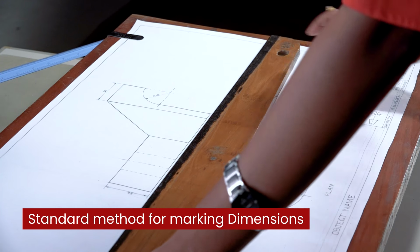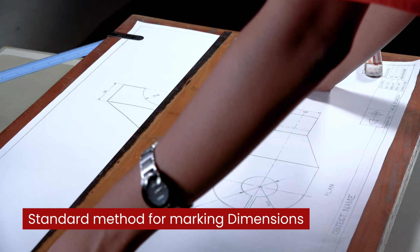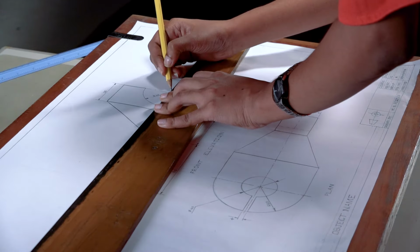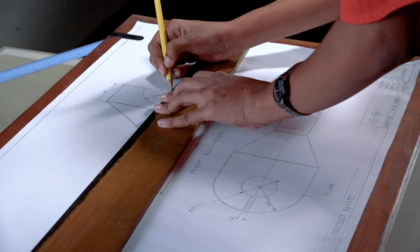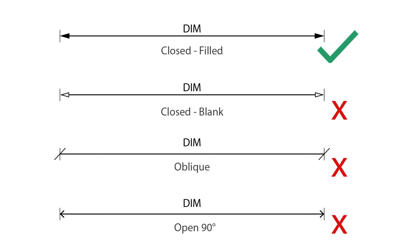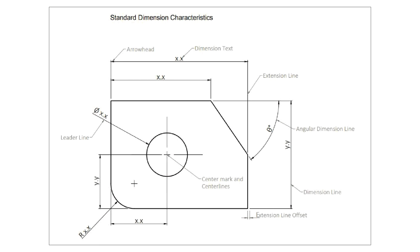This step demonstrates the correct method to mark the dimensions of the different features according to ISO standards. The font size of the dimension must be 3 mm. These are incorrect ways of marking dimensions. Radius, diameter, horizontal and vertical features all have specified ways of marking their respective dimensions.